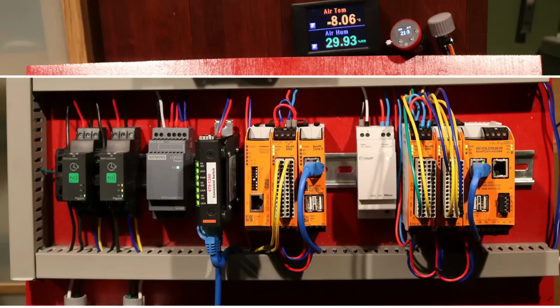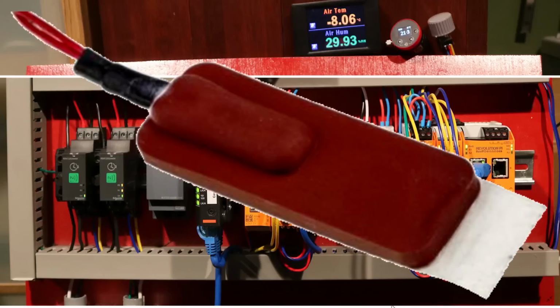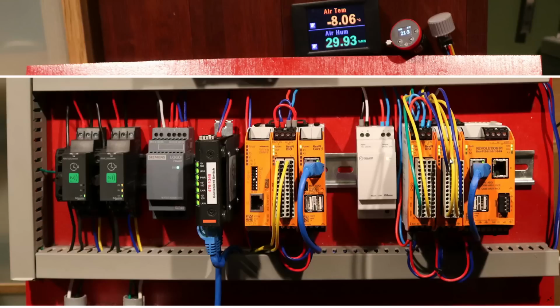And the next item is a rotary encoder, which is connected to two of the digital lines right here. And this module will be configured to actually support the rotary controller so that when you turn that dial, it will either increment or decrement a counter, which you can have access to through your programming to see how much the knob's been effectively turned. One of the other inputs on this analog module, you can't see it so well here, is a resistance temperature probe, which is actually sitting below this module, which is measuring the temperature of the room as well.